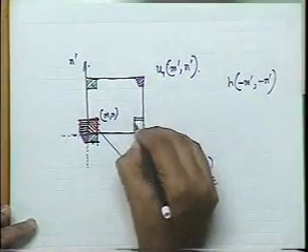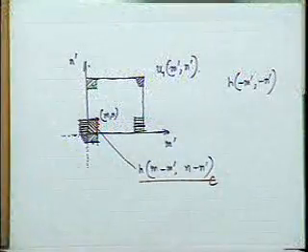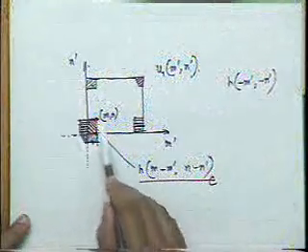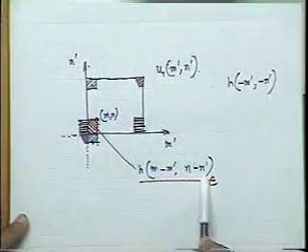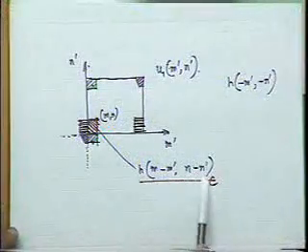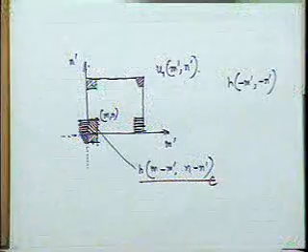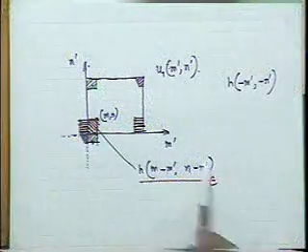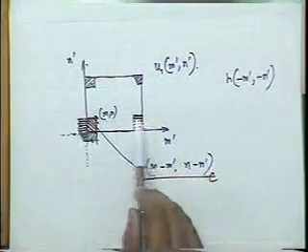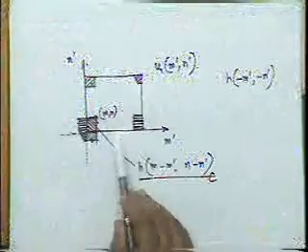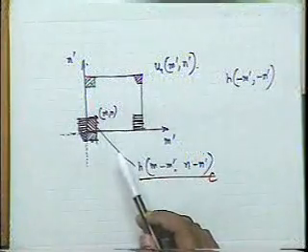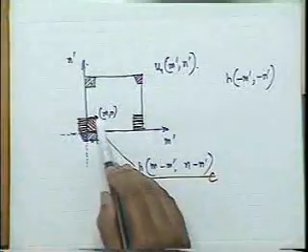this h of m - m' and n - n', these indices m - m' and n - n', are exceeding the image, then I will be considering the modulo function of this. After considering all these different portions, I have to do the multiplications and add them up, and that operation I have to do over the entire pixel range. So this was only for one particular position, but this function is to be swept over the entire range, and this is the concept of convolution.